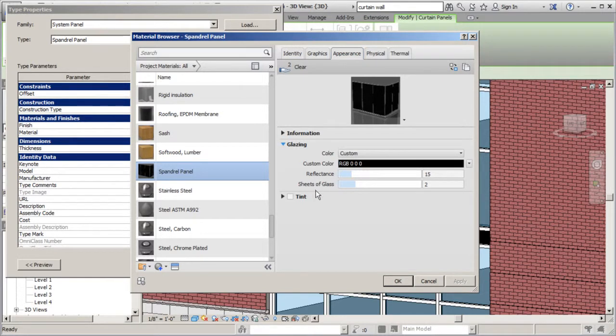So I think you have the option to actually come in here, and when I hover over this, it says adjust the number of panes. So for a double pane, you set the value to 2. By default, all these glasses are double pane. Enter a number between 1 and 6. So we can do single pane all the way up to 6, which is a little overkill, but we have that option. But for this one particular panel, I might want it to be just 1.